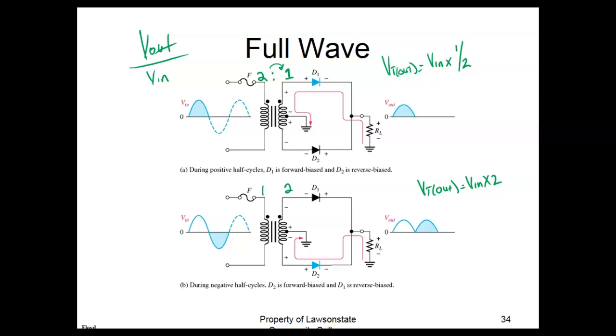There are several of these on the quiz as far as calculating this. Instead of giving you the actual output voltage, they give you an input voltage, like 120 volts, and then you solve it by the turns ratio. So everybody okay on that? Yeah. So it's out over in. Gains are out over in.